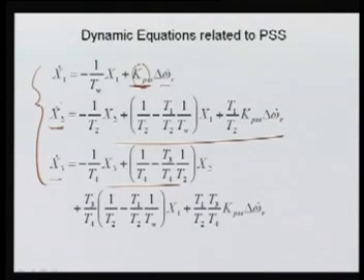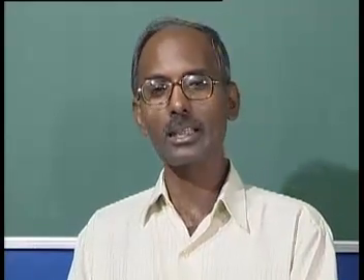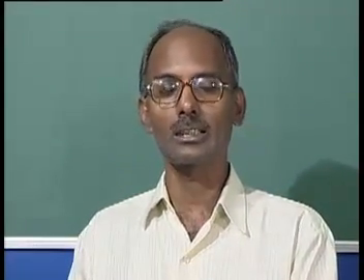Now this is very, very important: again, the tuning of the gain and the time constants of these power system stabilizers. If they are not tuned properly, even though they are used to improve the dynamic stability of the system, they will certainly have an adverse impact, and they may sometimes destabilize the system. In most of our Indian power system, all the generators are equipped with the power system stabilizer, but still they are not connected to the system because their gains and time constants are not tuned properly. They were creating more oscillation, so they are not connected to the power system.